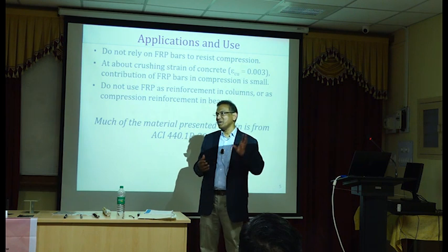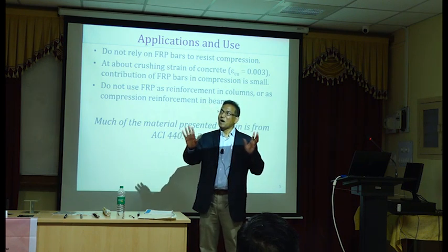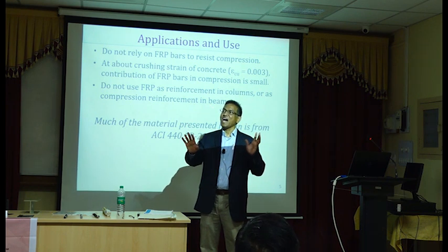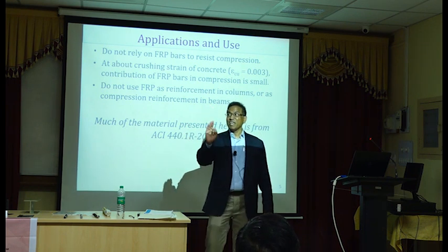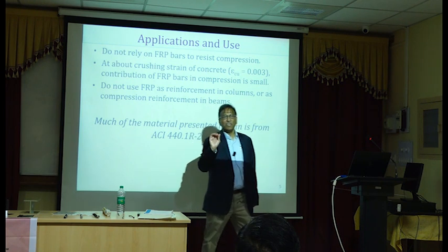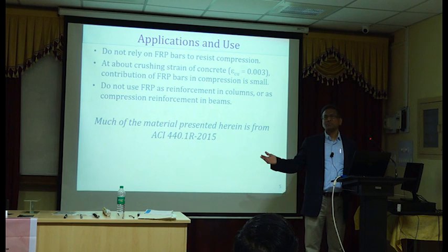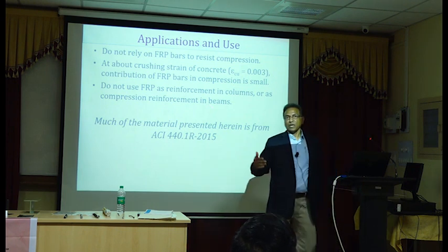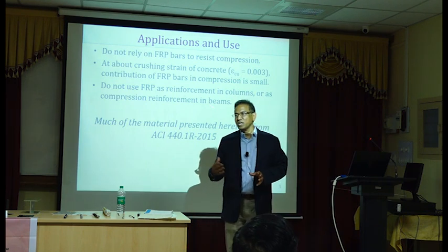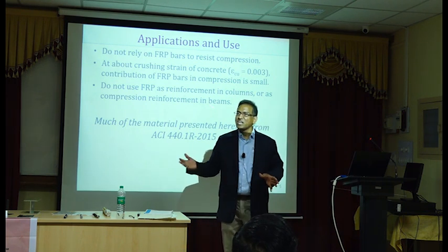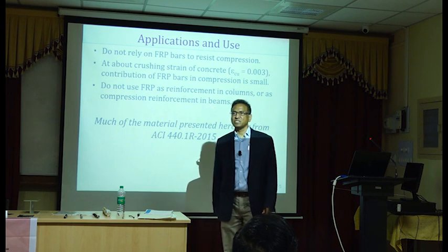So if you are designing based on cube strength, you are already inserting 20% of unsafe condition. That's what I'm saying. I'm trying to caution you, okay? Because without knowing that, if you just use the ACI code, it assumes that it's a higher strength concrete. But if you are complying with the code using cylinders, that means you are already introducing a 20% difference.